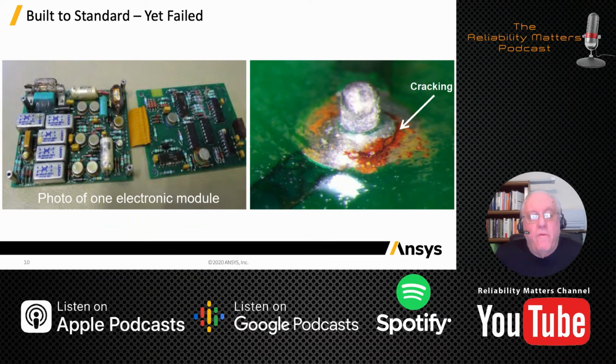Now, the flight control avionics for all aircraft are very redundant. In this particular aircraft, it was a triple redundant system. But what happened when he did that in flight, let's pull the circuit breaker and reset everything, is that the voting circuitry couldn't vote anymore, because what it did was it looked at the triple redundant signals and systems, and if one disagreed, then it discounted that, stayed with the two that did agree, and that allowed you to continue flying.